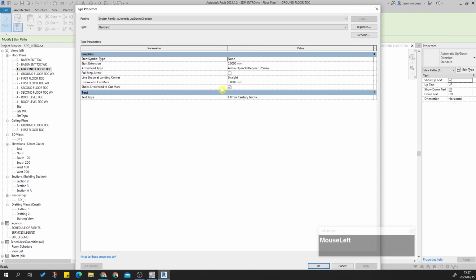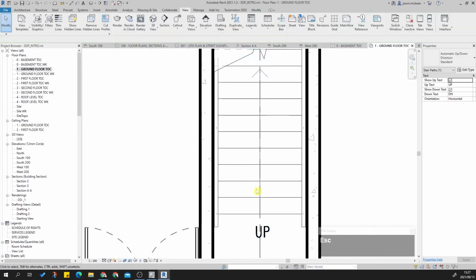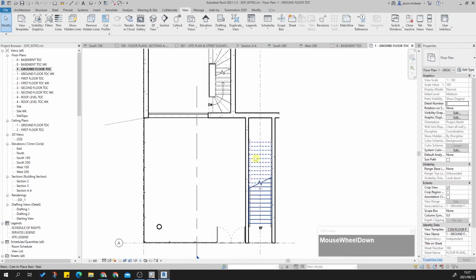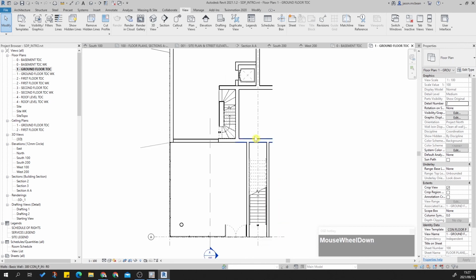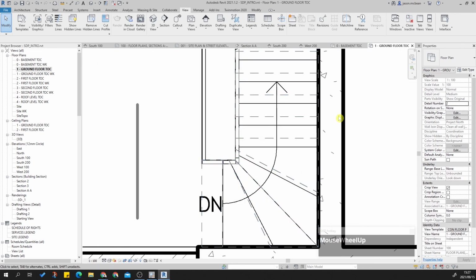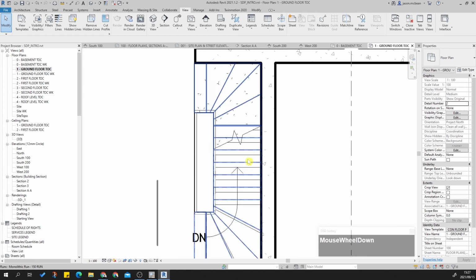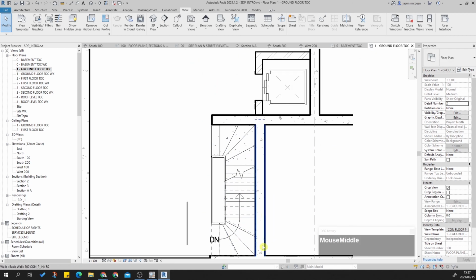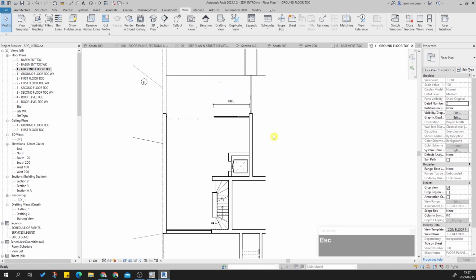You can change this distance to cut lines and all those types of things. And that's just the line in which it cuts. So technically we could have a store underneath here, but for this exercise, I'm not going to worry about it. But you can see the line weights are working great. Your hidden lines are looking really good because it's showing you there's a staircase above. These do get tricky to read, but you'll make sense of it.